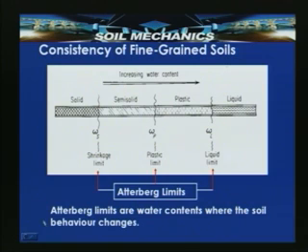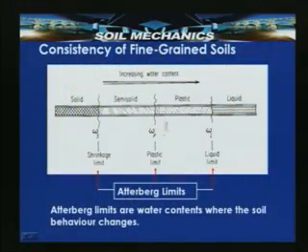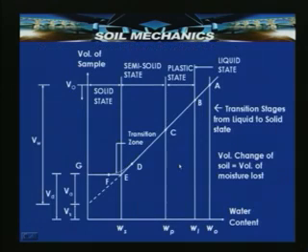So, Atterberg limits are nothing but water contents where the soil behavior changes. Here, from solid to semi-solid state there is a change in behavior, from semi-solid to plastic state there is a change in behavior, and from plastic to liquid state there is a change in behavior. Mostly, natural soil deposits occur very close to the plastic limit.